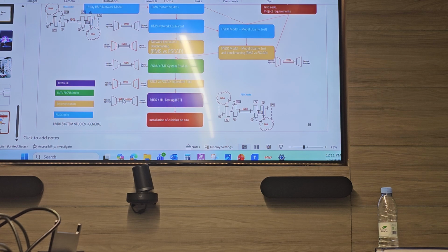So then you energize the neighboring substation, then you connect load, so voltage and frequency will change. Your system has to cover this, not disconnect or trip, and at some point you can synchronize with another device, another generator, a commercial generator, which is developing its own network there, and this is how, in case of blackout, you do restoration of your system.